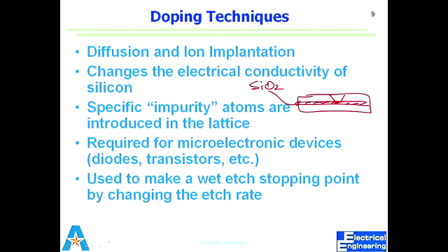The other way is implantation, where I bombard some ions, and instead of having this high concentration at the surface, I have the concentration somewhere in the middle, where you might have some high concentration. Implantation is like firing those ions at a surface and letting them penetrate through it.